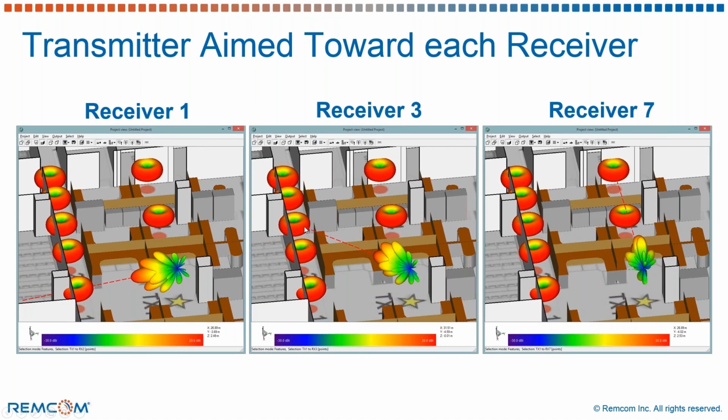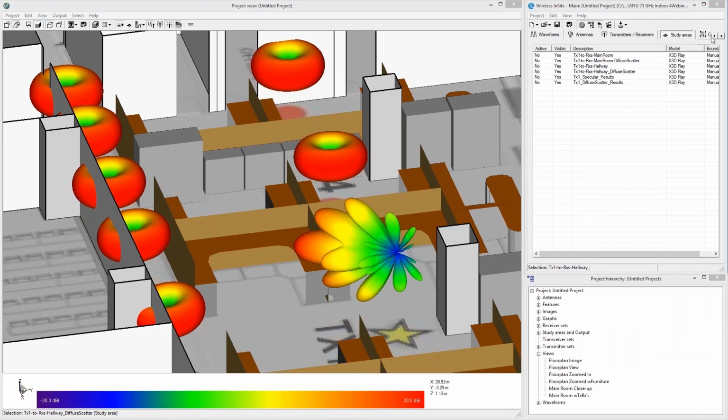So one of the first things that we might want to look at from these simulations is a series of paths to see where the paths propagate and what the multipath looks like. So going from the transmitter to the 4th receiver shown here, this display is showing all of the multiple paths in the top 100 paths that were calculated from this transmitter to this receiver. We can see that there's a great deal of multipath within this room, and that there are lots of paths that are going off to the side outside of the main beam, and so their power is a little bit lower. The paths in the reds, oranges, and yellows are the stronger power, and the paths in the blues are the weaker power, moving outside of the beam.